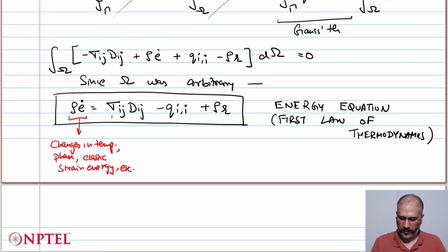Now on the right hand side, this first term is called stress power. So just like we have a force times velocity, or F dot V, as the power delivered by a force, stress double dot with D is like a power delivered by stress. So if a stress field results in deformation inside the body, that results in stress work. And since we're talking about rate of deformation, that is deformation happening continuously, that will result in a stress power. So without deformations, there is no stress power.